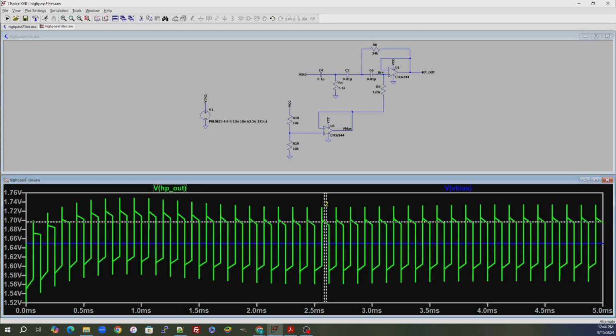And then I'd also have to take a second one and get an average down here, which would be somewhere around, like we'll just say 1.6 volts, right? So I'd have to get those two averages through an ADC converter, and I would have to then do math and calculate to get the peak to peak. So I don't want to do that.